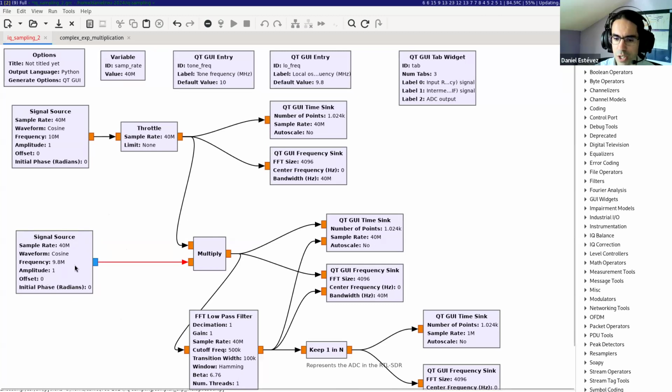Imagine this is just a shorthand for generating two sinusoids which are 90 degrees out of phase with two different oscillators, if you wish, and each of them is going through a different cable. But for simplicity in GNU Radio, we represent that with complex signals. We know that those are two real values.